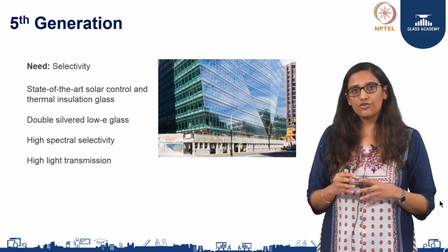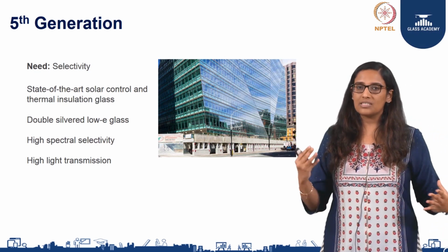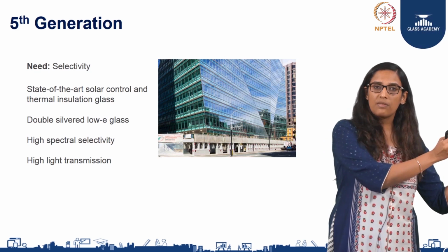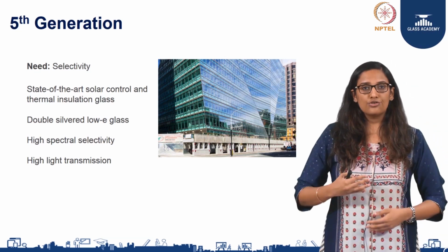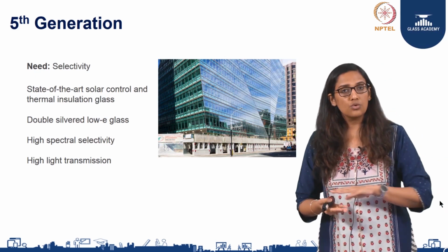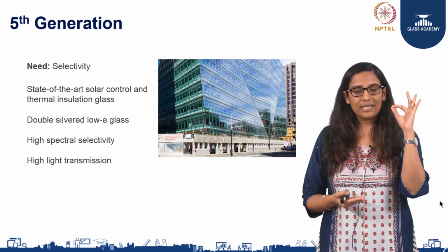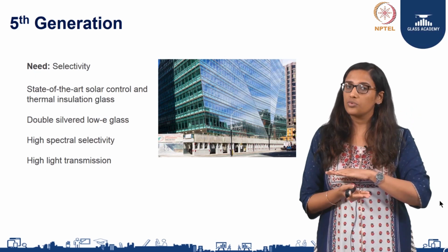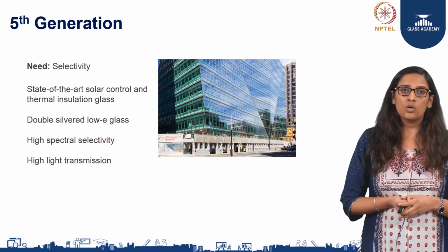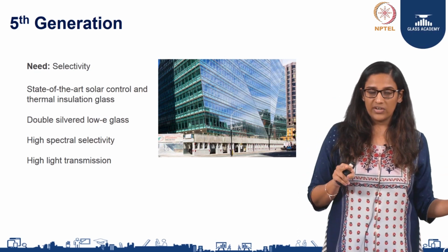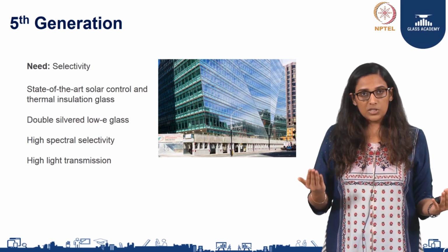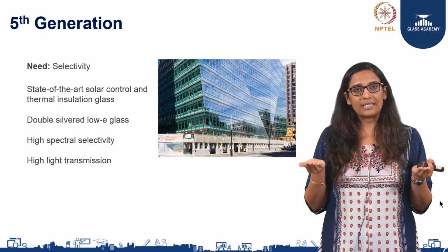Well, the fifth generation of products was really state of the art because it went on from the fourth generation where you had one layer of silver to moving on to depositing 2 layers of silver in that nanometer thick coating that you were having on the glass. When we were able to deposit 2 layers of silver as compared to the first layer of silver, the performance of the product improved significantly.